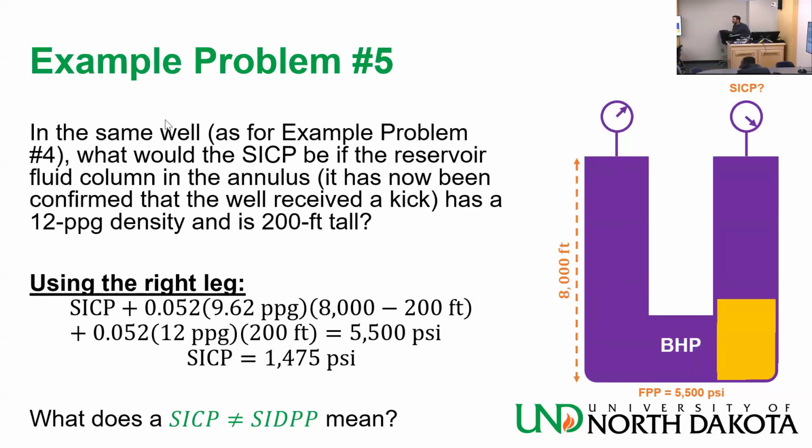But I don't think, if we are looking at the weight of the formation fluid that we enter, that any one of them can be higher than the mud density, because either gas or oil, they are both lighter than water. What determines why you got a kick, and we are going to see that later, maybe a little bit of a premature mention, is that my BHP was smaller than my FPP. My FPP doesn't care what kind of fluid it is, or what density. It cares what the pressure of that fluid was. That's why I got a kick.